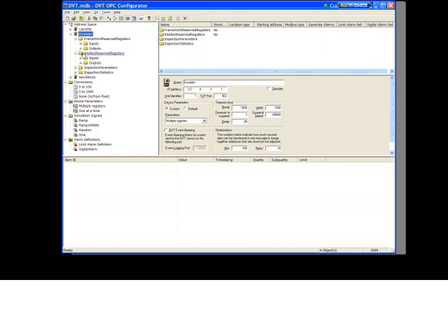In Framework, the Modbus registers and the general purpose DVT registers share the same space in memory. So because of that, and because the DVT OPC configurator is in terms of Modbus registers, you will have to make that conversion only for Framework and only for general purpose data transfers.